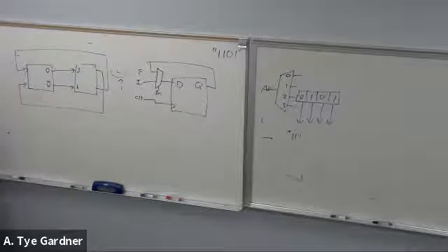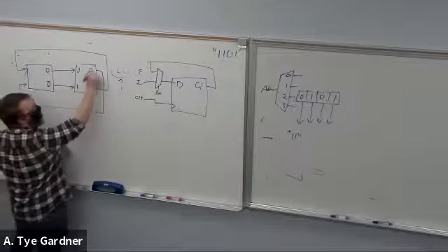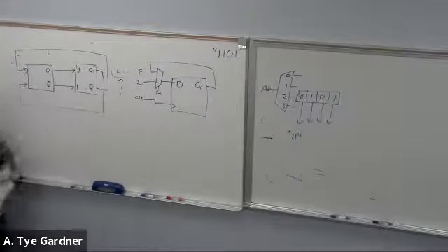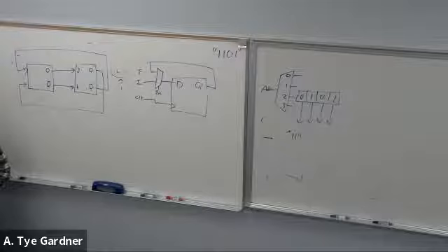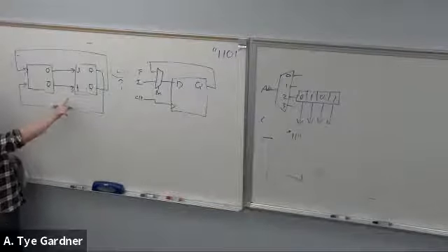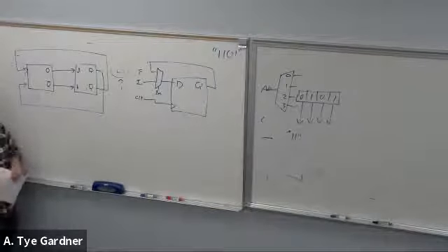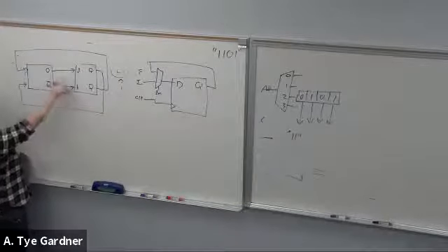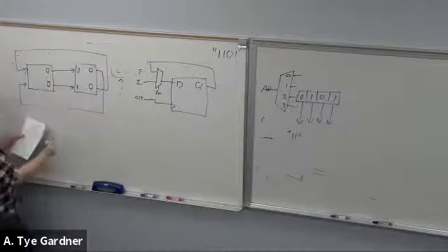If they didn't cross over, it would be kind of a boring system, right? But that flip means that all of your inputs are always opposite of each other, right? So I'm always doing a set or reset action. I'm never doing a toggle action, right? We're never doing a hold action for that JK flip-flop. And moreover, it takes 2 clock cycles for it to take place, because this transition is just straight across. It just holds. So you end up with